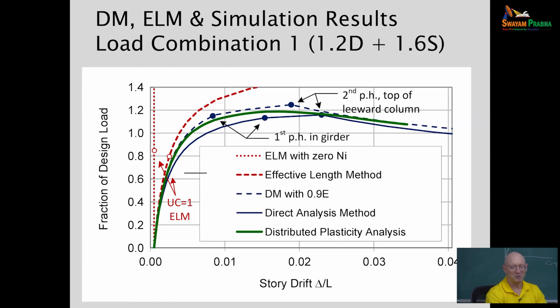If we're getting close to the failure of the frame, the deflections are going to start to get large because of amplification. And that's physically what's happening. If you're starting to collapse a structure, it doesn't collapse because suddenly it bifurcated. It collapses because I'm starting to get more and more bending, and now this thing is really moving.